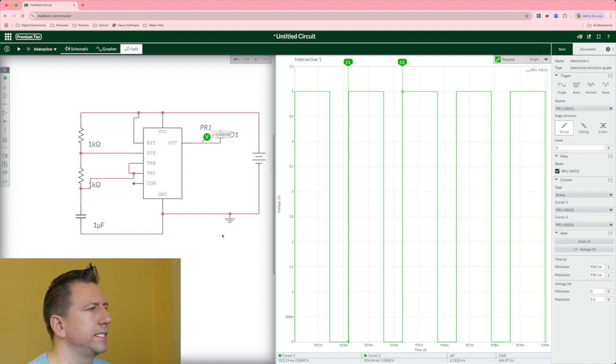And when I did that and I made the graph here, this is a triggered oscilloscope graph, and we're looking at the signal here. So what I'm able to measure easily off this graph is the voltage and the time. And so we have a 5-volt signal, and I can measure the time it takes to do 1 full cycle. So 1 full cycle here will give me the period. And what's 1 over the period? The frequency. So we can check our frequency.